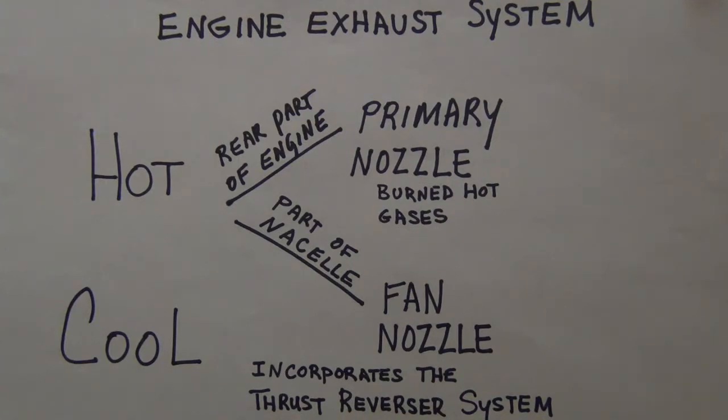And you've got the deploy switches there, so all that chain of communication electronically, electrically, mechanically is being done. Green system, yellow system. Green system is for your engine 1, yellow hydraulic system for engine 2. And that's where it's drawing that power. Your shutoff valve is located upstream of the hydraulic control unit. And that shutoff valve, what is it doing? It's basically creating a locking system for the thrust reverse system.